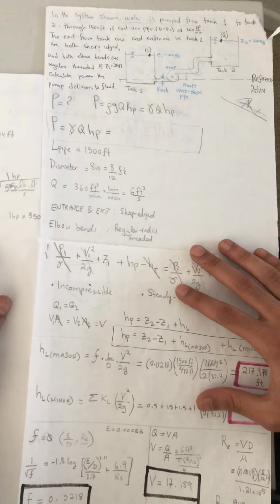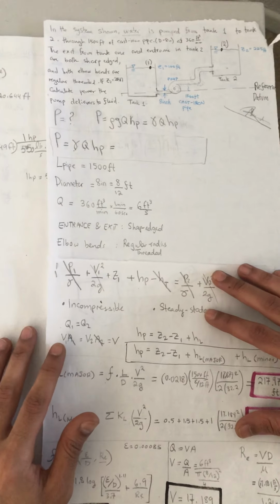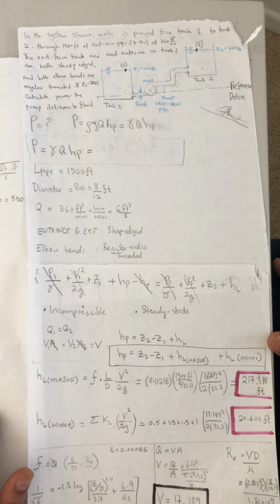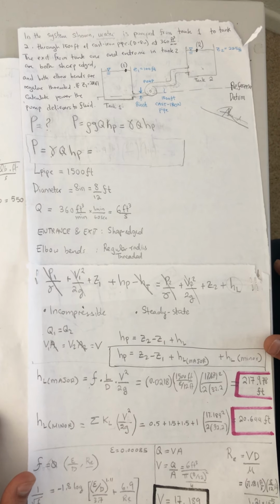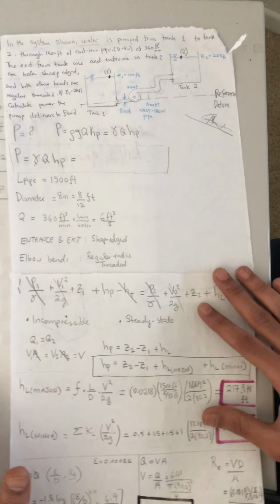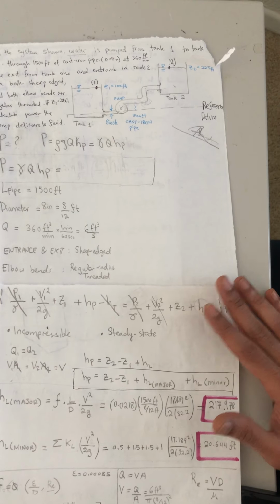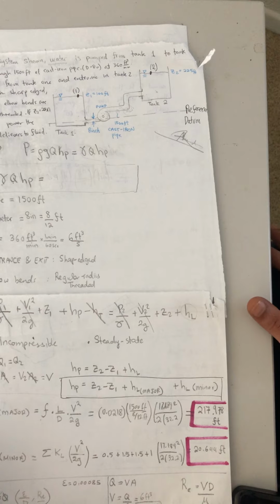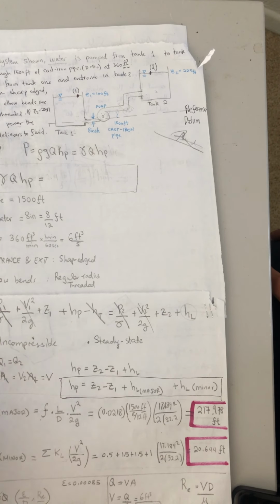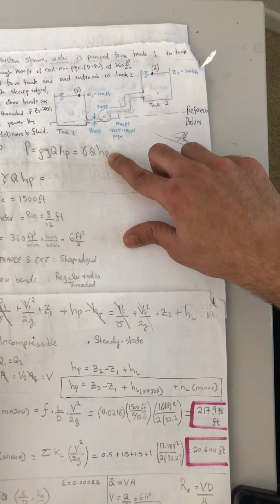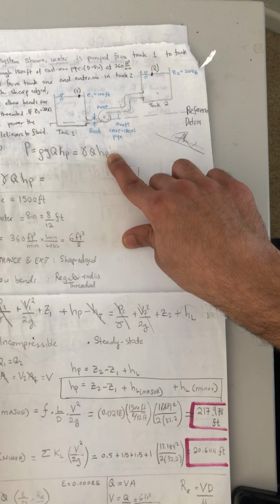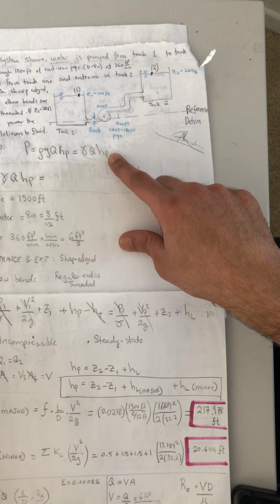So we will go over it again, step by step. I hope I covered everything. We did say that our problem statement wanted us to determine the power delivered by the pump, and we have found the power by using the performance for the pump equation. We are missing an unknown value, which was the head gain, and the head gain is nothing but the height at which a pump can raise water.